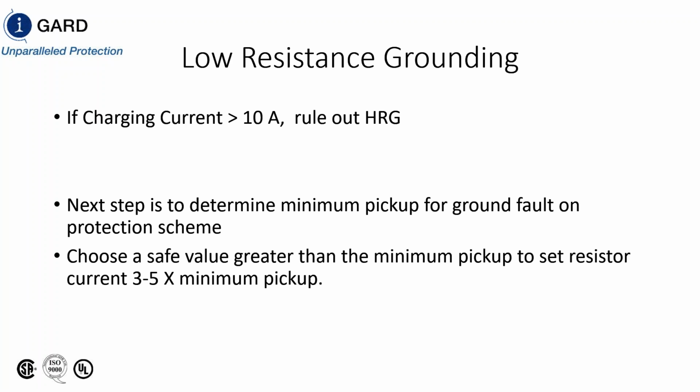So then we have to choose a value greater than that to limit the current to, in case you have high impedance faults, because we don't want the resistor to get hot and perhaps burn up.